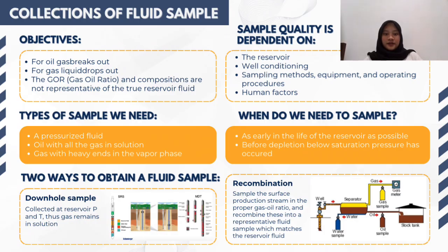SRS, single phase reservoir sampling, is a sampling tool with a buffer fluid mechanism to maintain the pressure. An MDT, Modular Formation Dynamics Tester, is a system used in wireline logging to collect fluid samples from the wellbore. We can take a look at the picture on the right.